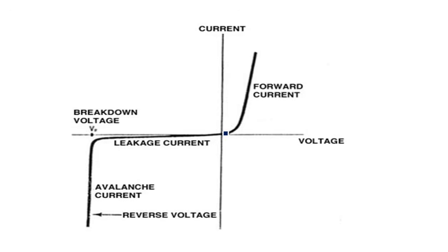Now I have already explained at the start of this video that in the forward bias characteristics there is no difference between the characteristics of the normal diode and this IMPATT diode. They are the same, but everything else is in the reverse bias condition. In the reverse bias condition, up to a certain voltage, the breakdown voltage VBD, as the voltage increases in the reverse direction, the current slowly increases.